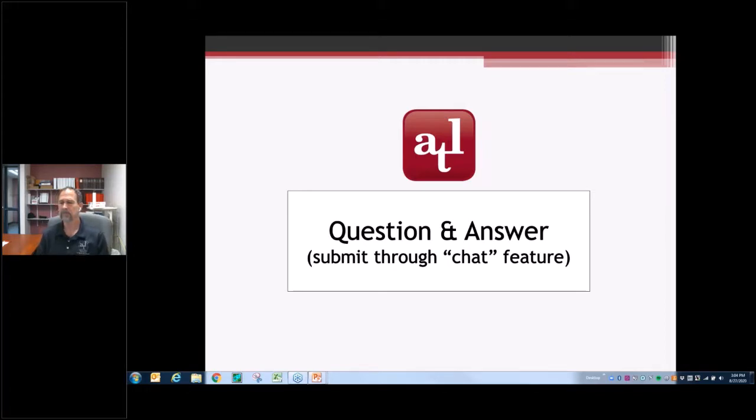Is there any method to detect corrosion in rebar? There's a method called half-cell testing that you can evaluate the potential for active corrosion.